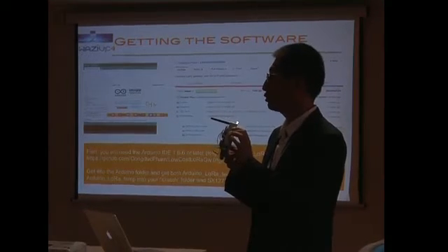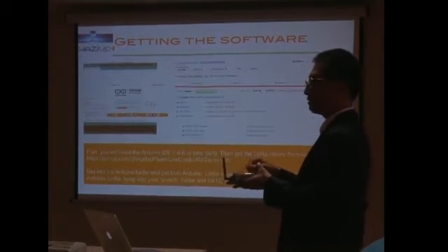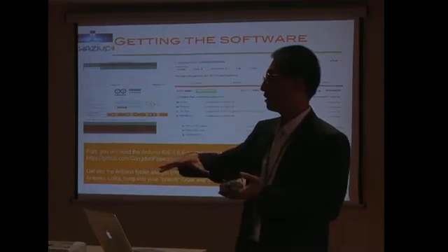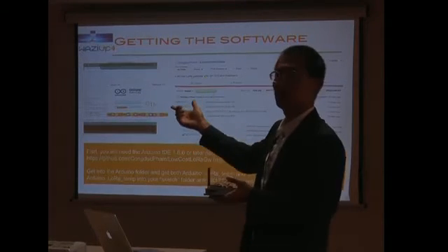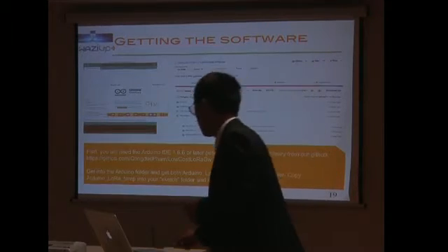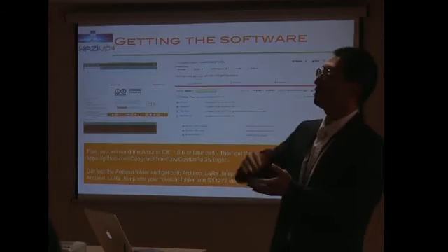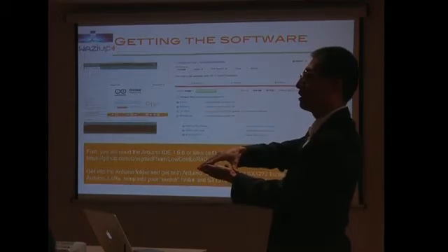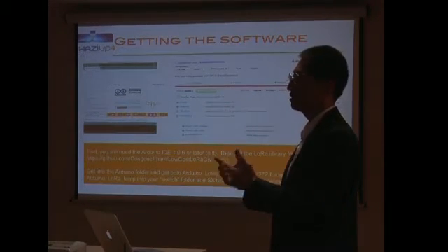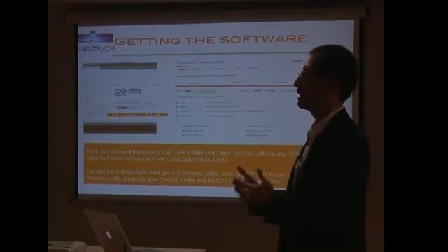Not for a year if you're using SMS. So this is completely different. But if you want to use SMS, you can put a 2G shield on the gateway that sends SMS instead of uploading to the cloud. Another method that might be more cost effective is to upload the data to the cloud and then have an application that takes data from the cloud and sends SMS from a computer. That is more cost effective if you really want to use SMS instead of other kinds of interaction.